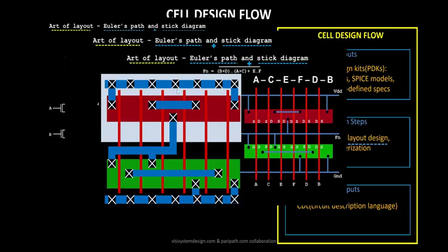And again, the metal layers. For example, it has got metal 1, it has got polysilicon and so on. This is built on the metal 1 layer, and it could be taken up to metal 2 or metal 3 layer depending upon the requirements from the user defined specs. So that's a layout drawn using the circuit that we have over here, and using the DRC rule inputs that we got from the input stage or from the foundries. So that's the next stage.